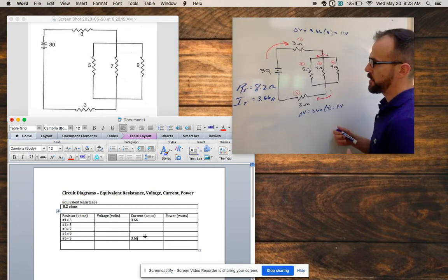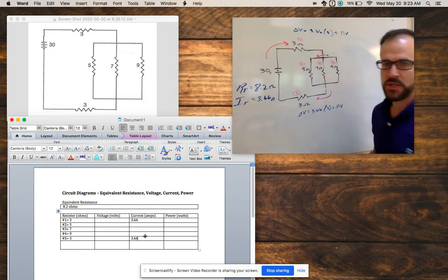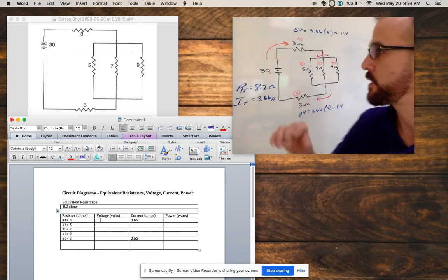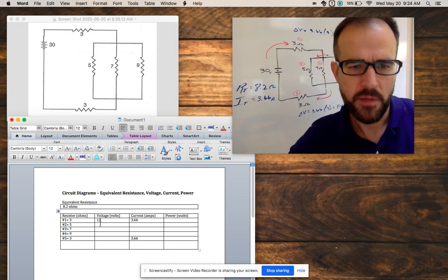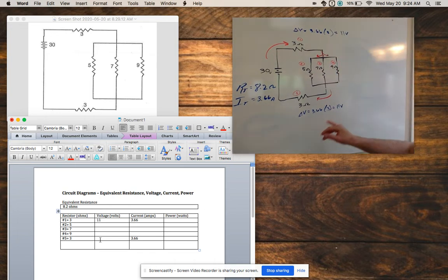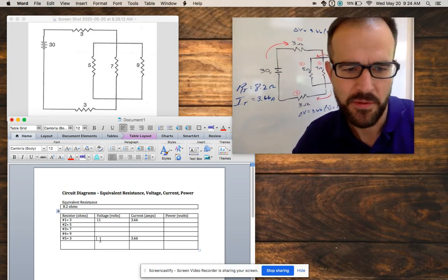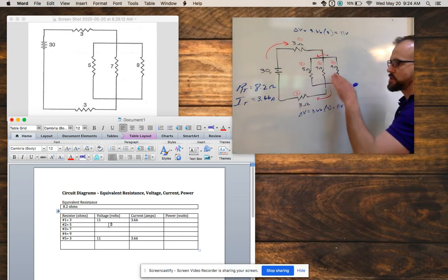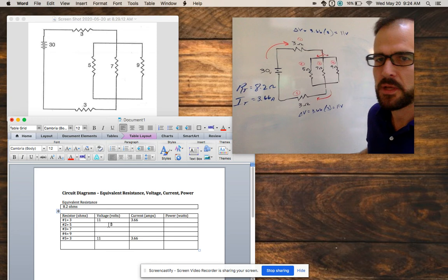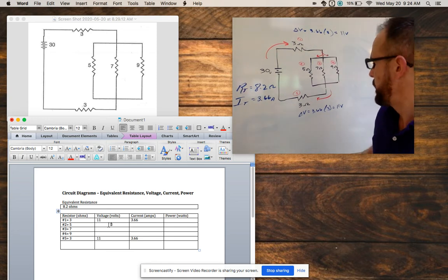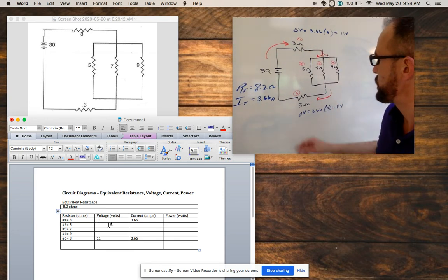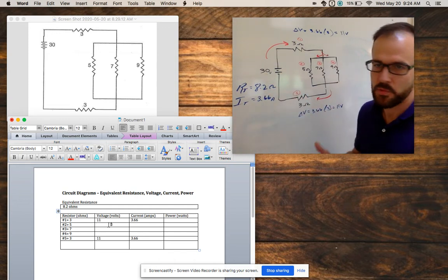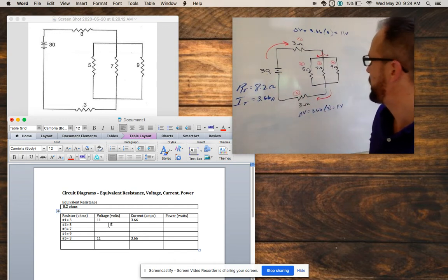And that allows us to figure out what the voltage drop is for this section here. Maybe we'll fill in the chart so far. So we got 11 volts and 11 volts. That takes place at 1. So 11 volts, and that also is the drop, we call it, down at the last element. And then whatever's left of the battery, each one of these will have that same drop because things in parallel have the same potential difference drop. So 11 and 11, 22, it was 30 volts to begin with. So 22 of them get used up with a little rounding at these two elements.